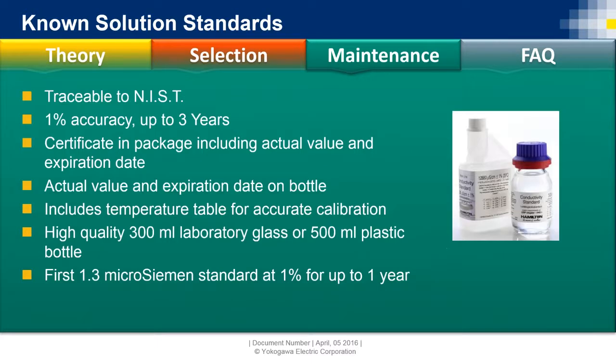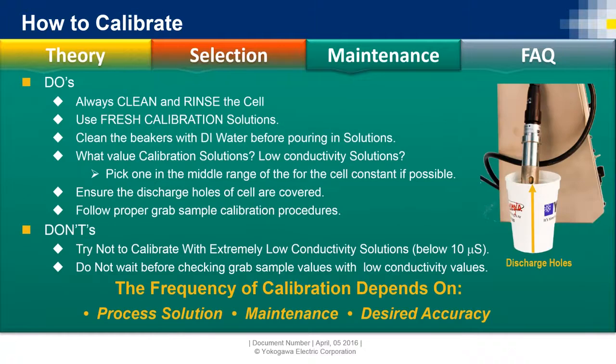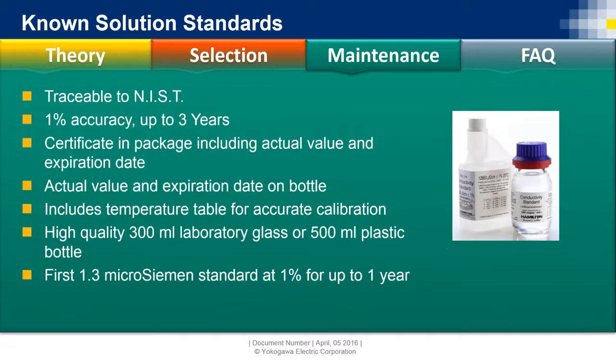And then what we'd say don't do is, if possible, we want you to do air calibrations below 10 if you're in ultra pure water, and we'll show you why in just a moment. So most people nowadays are kind of moving to a pre-made solution, a NIST standard solution. These again are Hamiltons that they offer. These are pretty accurate.